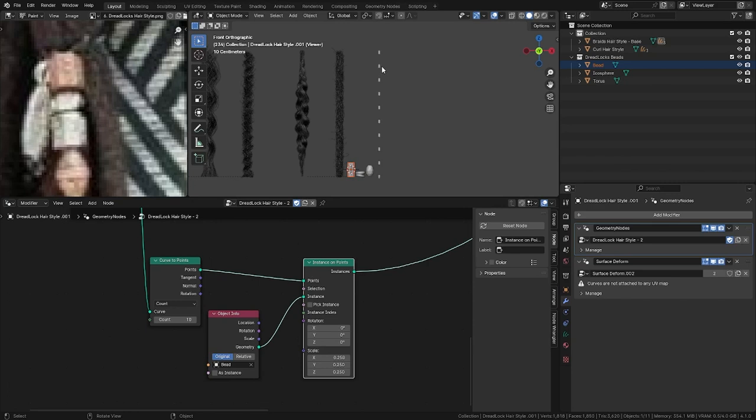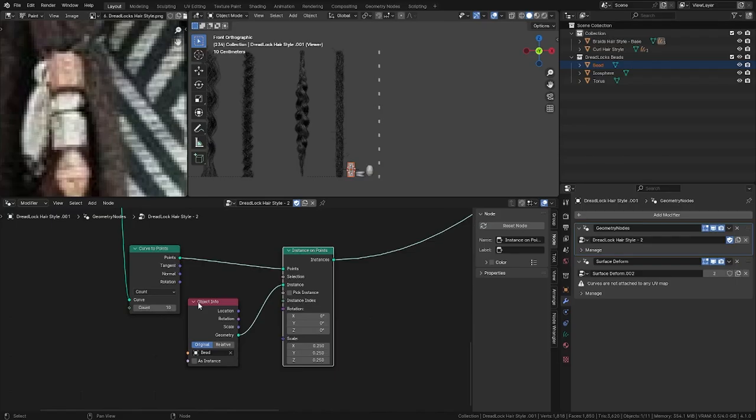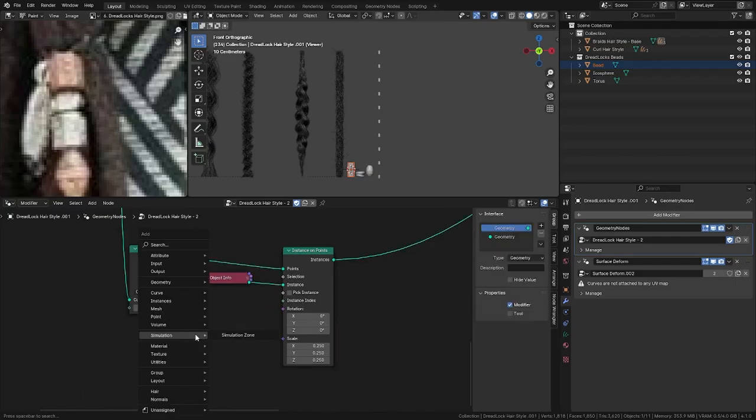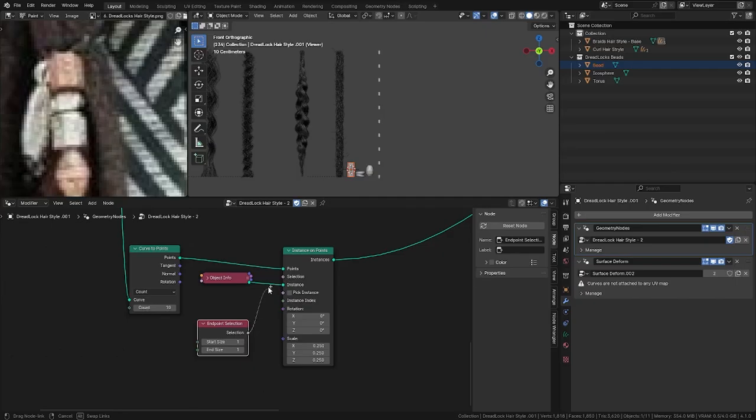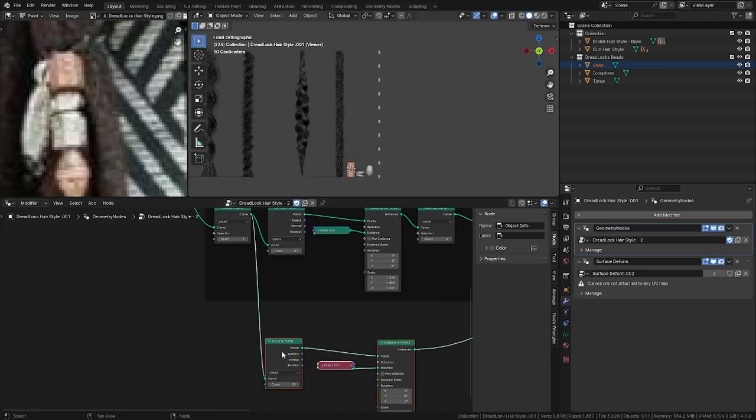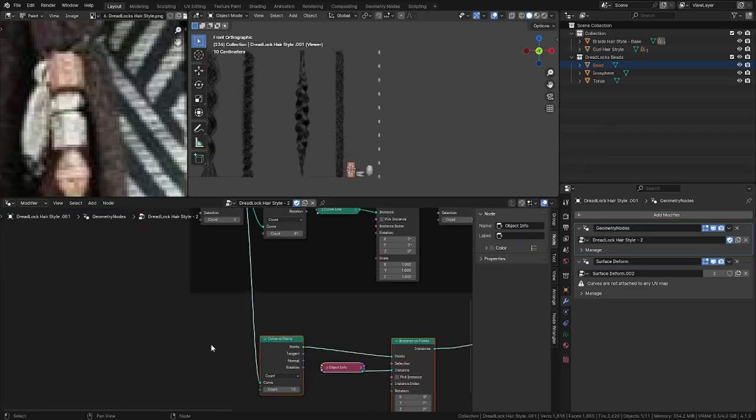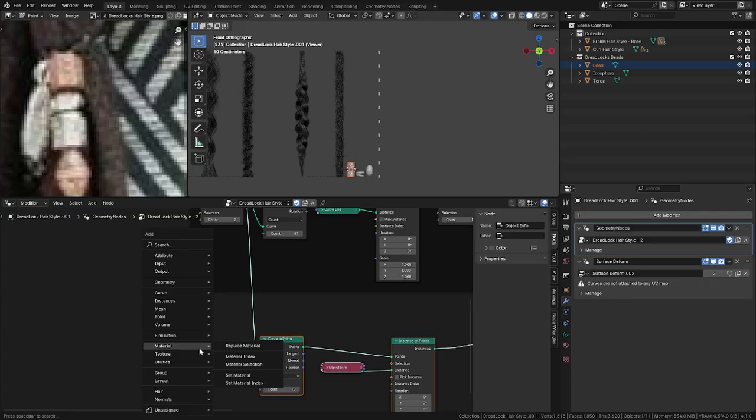So what we're going to do is use a selection. So here in our selection, I look for selection, curve, endpoint selection, then go here, start, and I found this is not working. So what we'll do here, before we change the curve into points, we need to trim this.